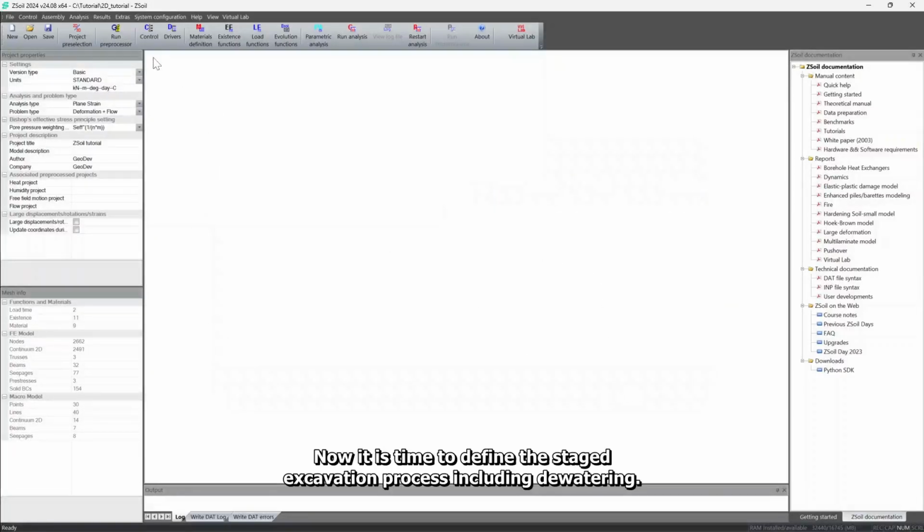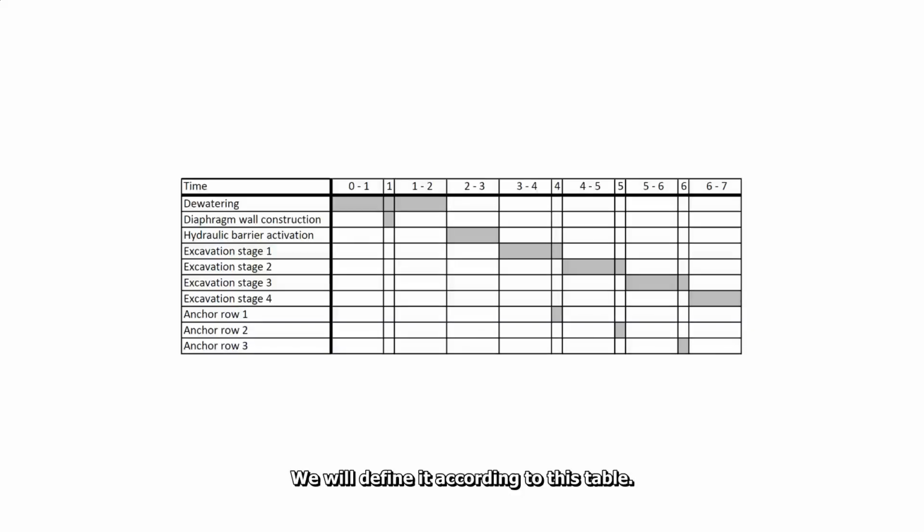Now it is time to define the staged excavation process, including dewatering. We will define it according to this table. The dewatering happens between t equals 0 to 2, with construction of the diaphragm wall at t equals 1. Between t equals 2 and 3, the hydraulic barrier will be activated. Then follow the 4 excavation stages from t equals 3 to 7, each within a time span of 1. The anchors will be set and pre-stressed at the end of the respective excavation stages.